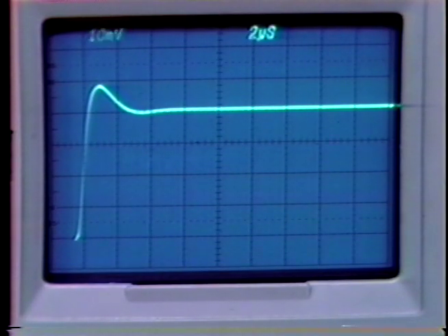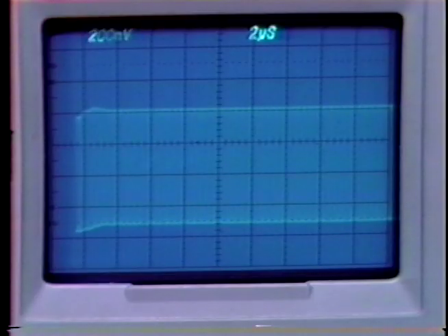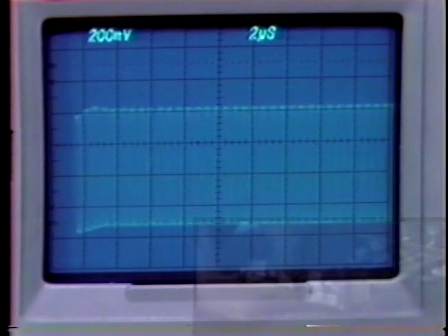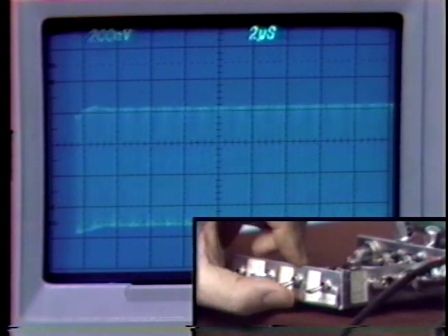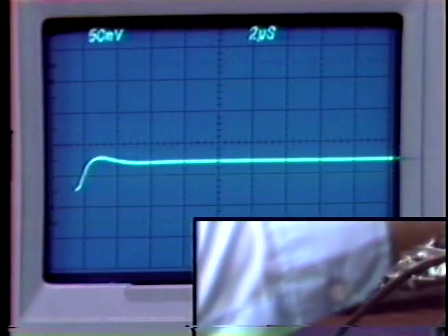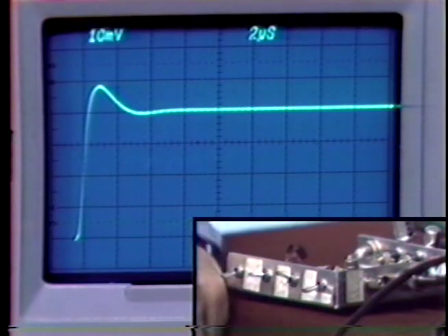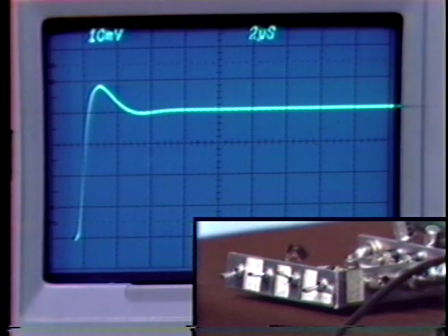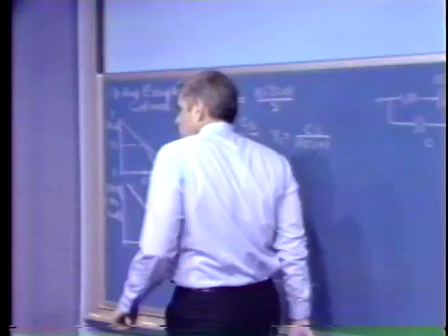The amplifier will oscillate even if we load it with a capacitor other than the intended one. If we go to the 0.1 microfarad capacitive load, once again the amplifier is oscillating, presumably at a different frequency, but once again oscillating. So if we go back to the capacitive load we designed the compensation for, things are fine, but if we change the magnitude of that capacitive load, or if we eliminate it entirely, things get much worse. So that's one of the problems with this form of compensation.